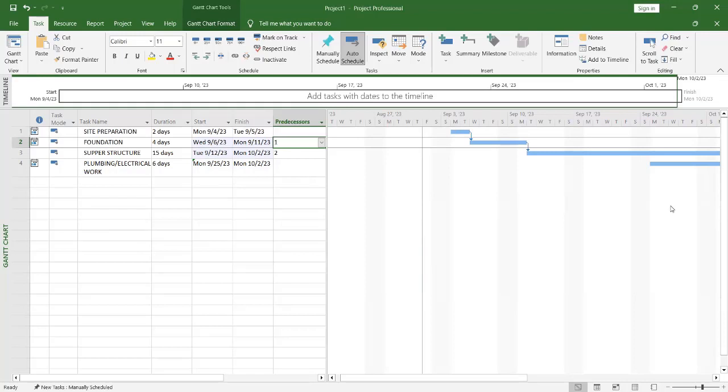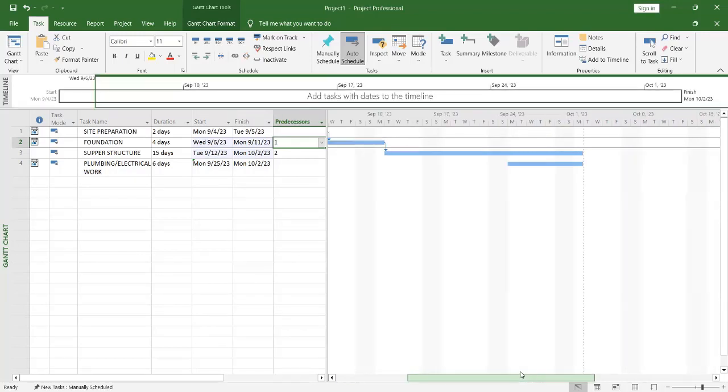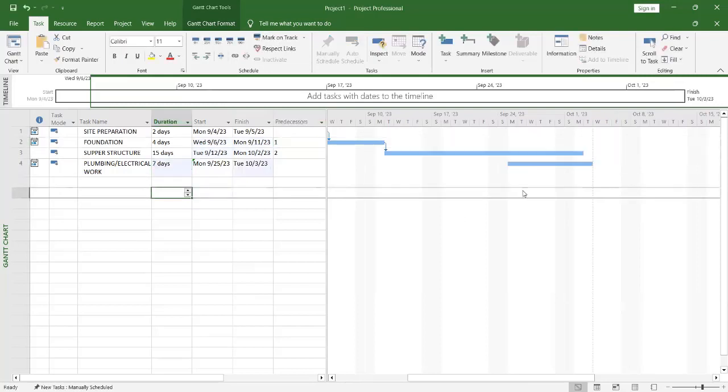All right, so we have specified that plumbing should start and finish on the same day as this superstructure, and the other electrical activities. Or we can decide to let it take 7 days, so that there will be 1 day after the superstructure, so that you can do your pressure testings and all that for your electrical, depending on the sequence, or your mechanical as well.